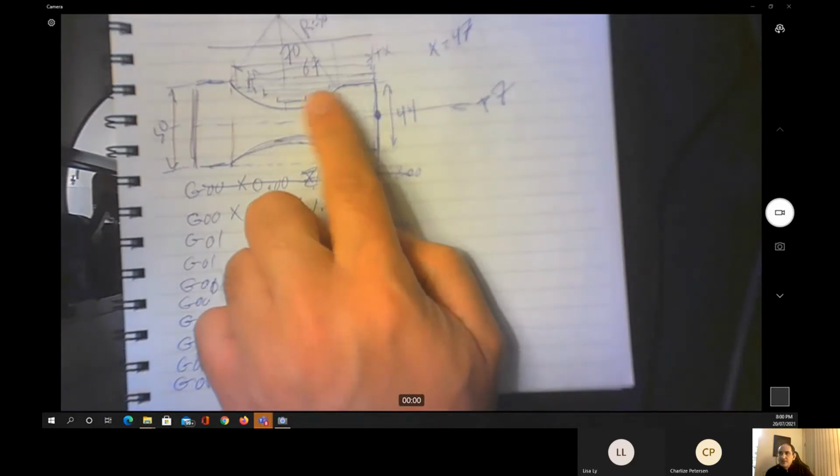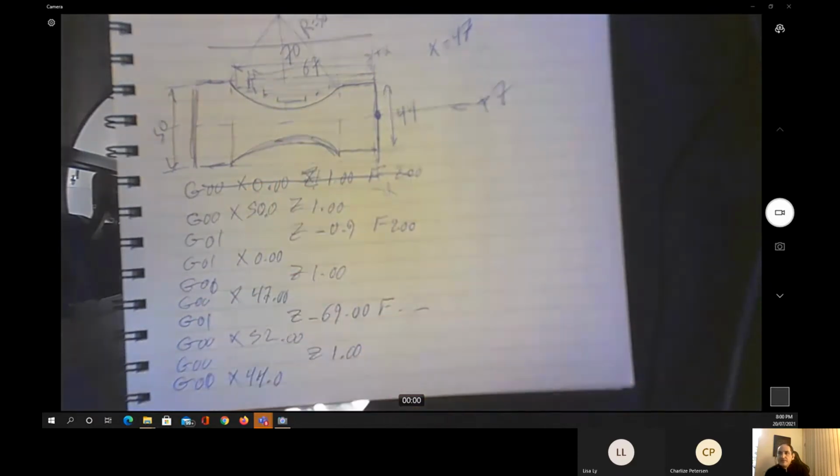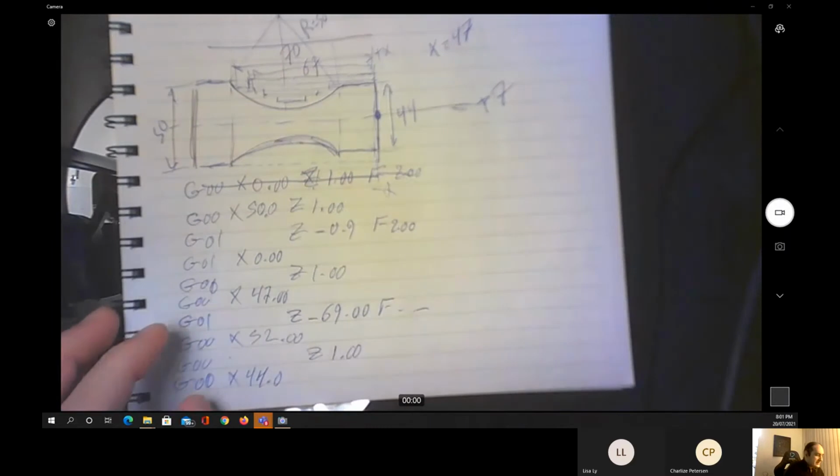And to cut such a shape, which you can see, oh, it's too simple, it's going to take something about 5 to 10 times the lines required if we're going to do a more complicated shape in the case of the milling operation. Because the milling can move into the depth directly, while this one needs to do it step by step. And that's what we call the canning or the cycle cut, until we're going to have the approximate shape by roughing. Then we can finish it by the finishing operation. Maybe we didn't cover that in the manufacturing engineering, but again, to repeat the same thing for them.